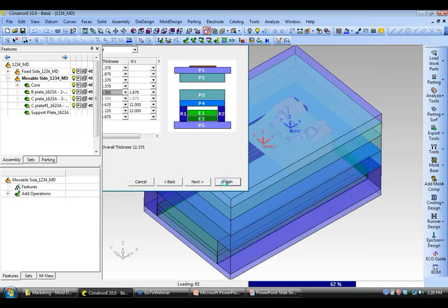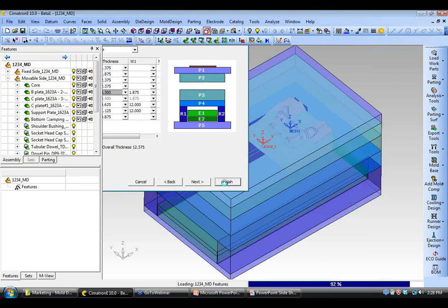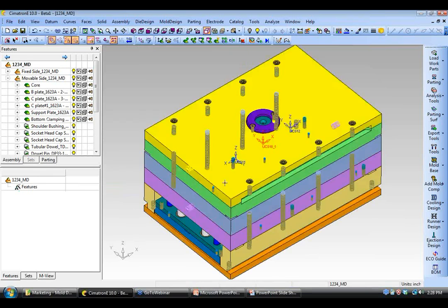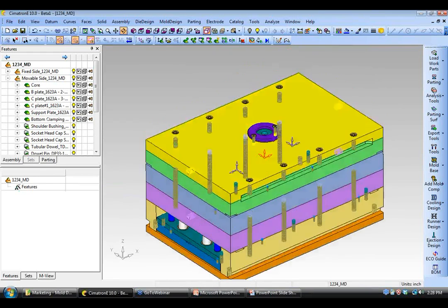I think one of the things to note also is you pick the standard from a standard mold base from PCS. You can also go ahead and pick that mold base, and then you can go non-standard and type in any of your sizes, whether it's length, width, or an odd-sized plate. You can go ahead and put that in as well, too.